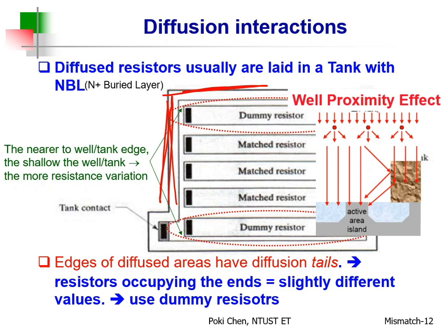So you can see if some go in that direction, then reflected by the wall boundary back to the well. What does it mean? At the boundary, you will get doping or implantation, not only from this direction, but also from reflection. So the doping or implantation concentration at the boundary will be higher than in the middle. Got it? That's it. Okay?